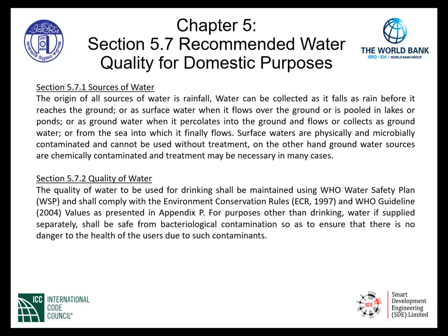Surface waters are physically and microbially contaminated and cannot be used without treatment. On the other hand, groundwater sources are chemically contaminated and treatment may be necessary in many cases. So this requirement, sources of water, gives us an indication of where the water comes from, possible contamination, and treatments that may be necessary in certain cases.